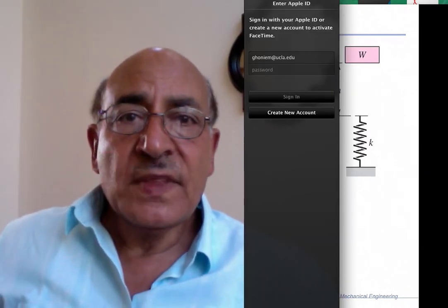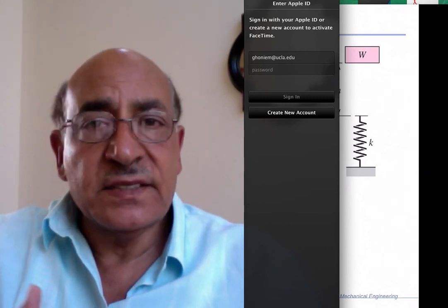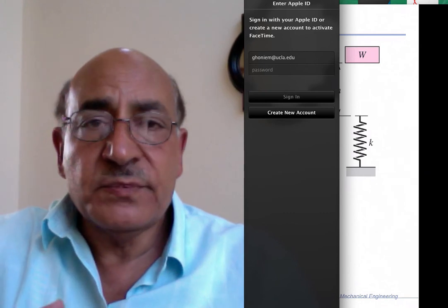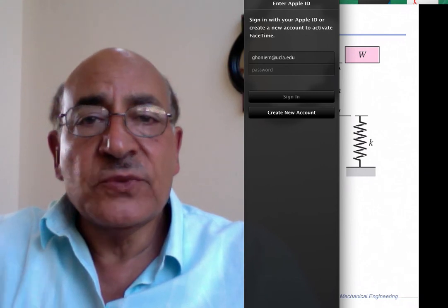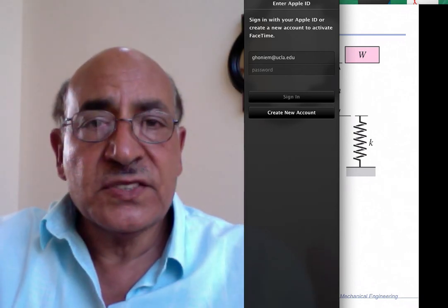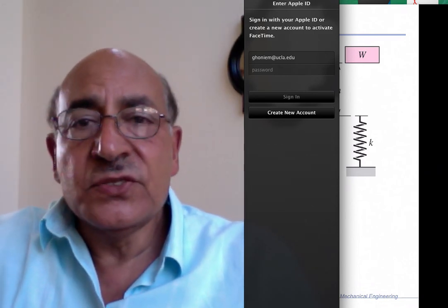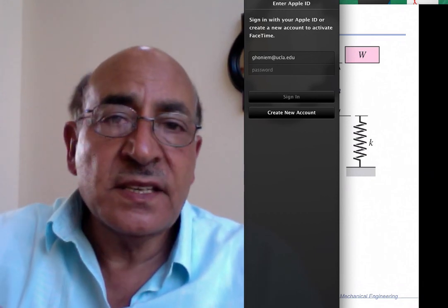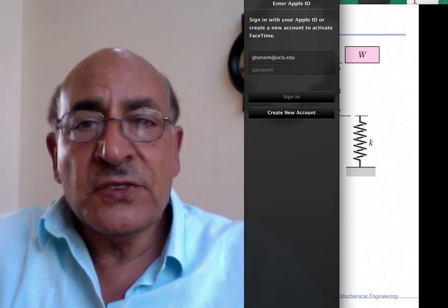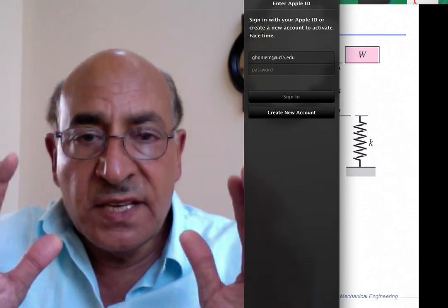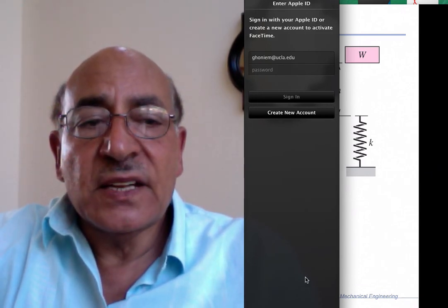in the member. So we have now all of the ingredients that we require to calculate deflection of various forms, either beams, indeterminate beams, curved beams, and so forth. And we are able also to compute very large deflections due to buckling. And the buckling can be elastic or can lead to plasticity. In the case of plasticity, then we use the Johnson parabola. And finally, if we have a dynamic load, how to convert this dynamic load to an equivalent static load and do deflection calculations for it. And with that, we're going to